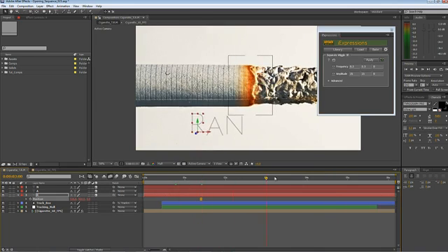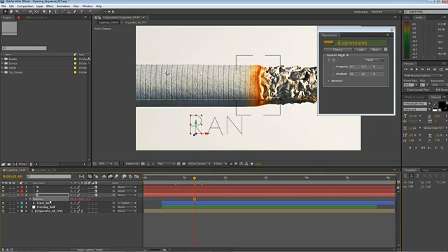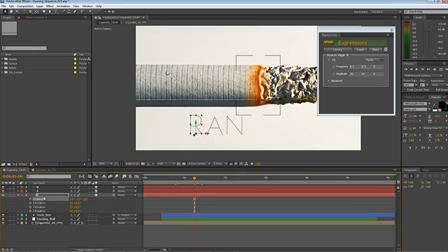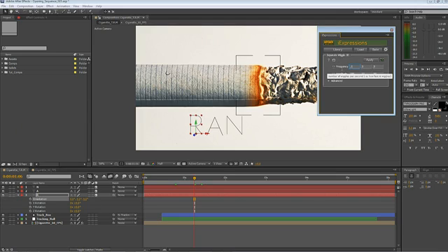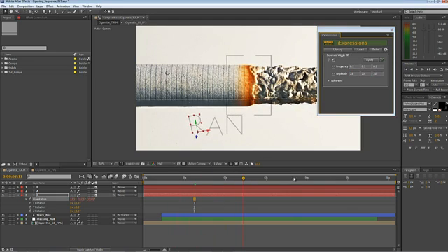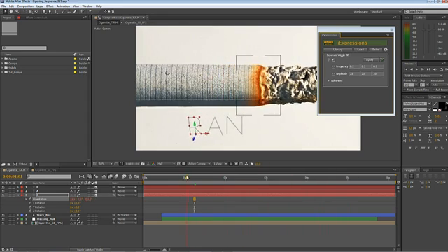How convenient. Now let's do the same for the rotation. Let's hit R and reset the tool, and we'll set it to 0.2 for the frequency on X, Y and Z, 25 for the amplitude X, Y and Z, and hit apply, and that's it. How easy is that?